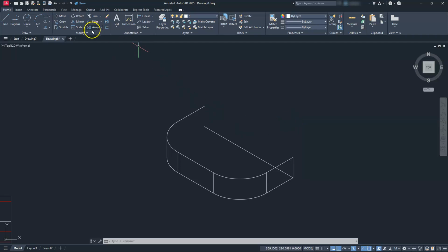So I'm just going to use the lengthen command. I'll go to modify. And I like to use many different commands here. I could have stretched that. I could have done some other things here. But I'm going to go to this lengthen. Then I'm going to tell it a delta. Type in 25. Enter. And then I'm just going to select that line there. Okay. So now that basically extended that line up.